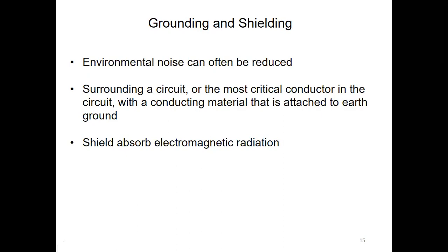Right? When we do this, shielding and grounding, the conducting material that we cover it with acts as a shield, and that shield absorbs electromagnetic radiation from the surroundings. When some environmental noise is there, it generates some electromagnetic radiation. Normally, that electromagnetic radiation would be absorbed by the conductors of the instrument.